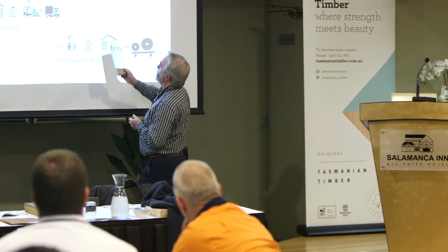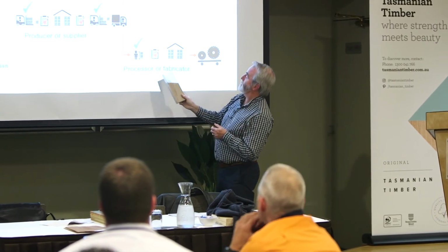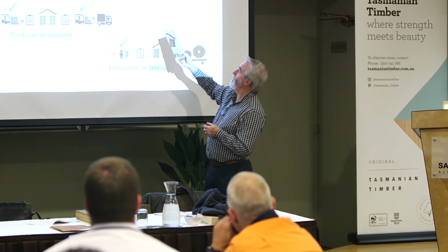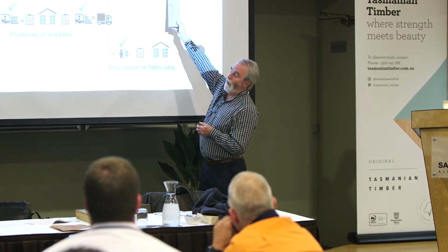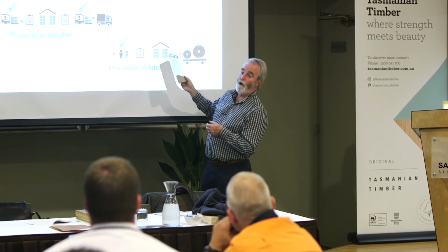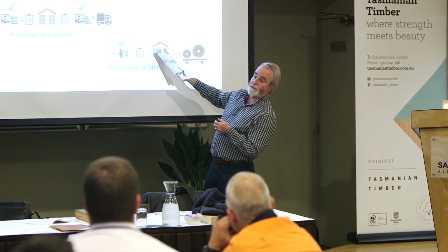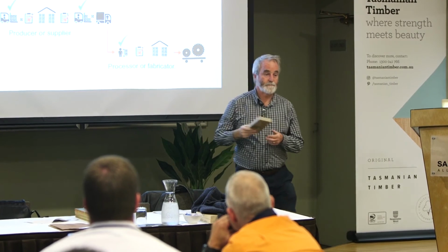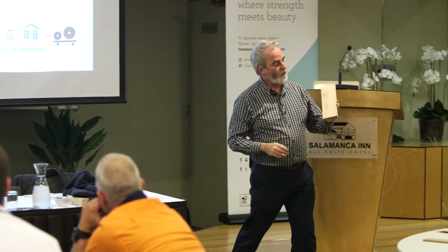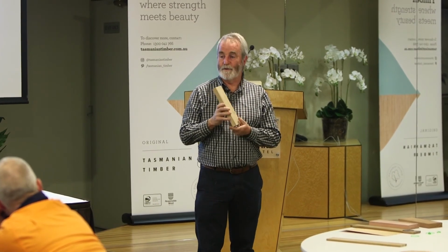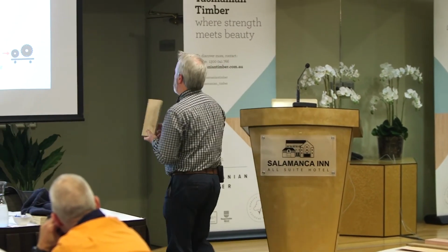If you get to a construction site or a fabricator's site, you actually want to be checking it there as well when you get it. And if you're not storing it for a long period, you want to check it solidly, protect it, and then use it. Now, if you put it in at the wrong moisture content, you can then get all sorts of problems. I'll show you one or two in a minute.